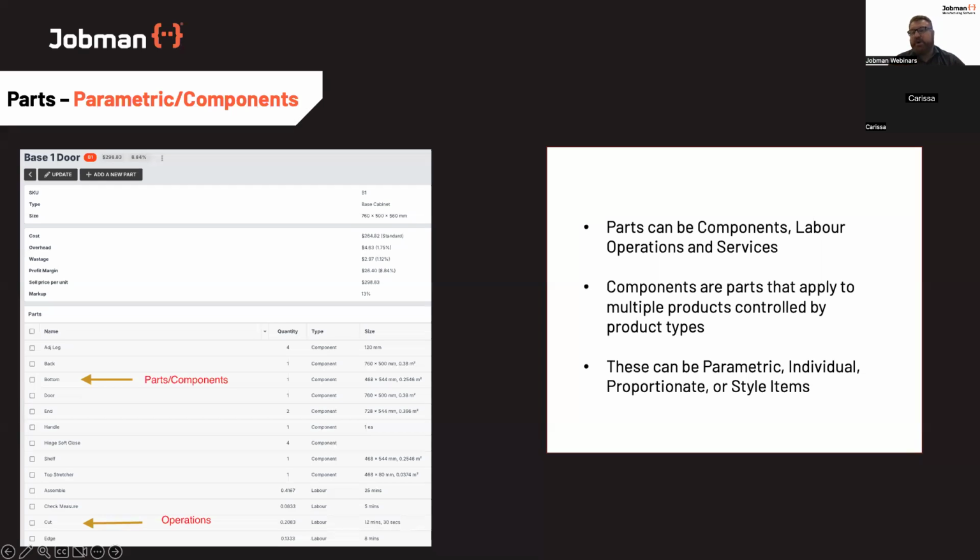And then all we have to do is go into those particular products and change any components that aren't quite right to parts. For example, the difference between our base one door and our base two door is two doors, two handles, and four hinges. So we add the components for hinges, handles, door, side, top, etc. And then we go into the base two door and change the measurements of the door because now it's not 100% of the product, it's 50%. We put two handles in and four hinges. And we can copy down really quickly. In a matter of minutes, once we've built the first product, we can build the 5 or 6 variations that you commonly use. So really powerful stuff. Really good, makes this setup really easy and a lot of intelligence.